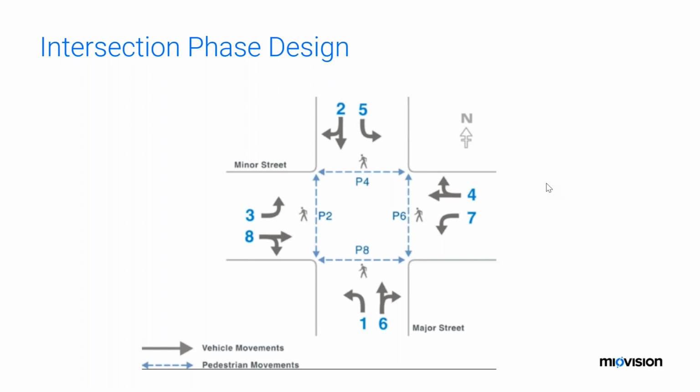In addition to the phase design, there are the pedestrian phases that tell you when you can walk and cross the road. So often when I'm configuring an intersection with someone, this is usually where I start. What is the phase design? Is there a document, or is there a way to help me understand if I say phase 3 left turn, which direction is that? So there's an obvious association of a movement to a phase to a detector zone.